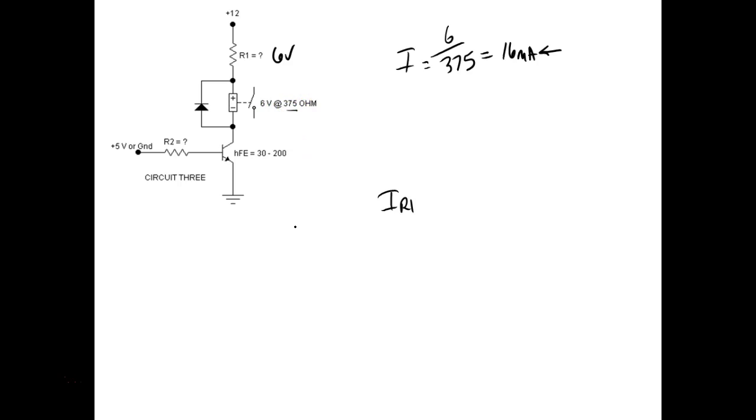We did this exact same circuit over at motor controls one time. We had a 120 volt source, and all we had was a 12 volt relay. Could we do it? Sure. All we had to do is see the resistance of the thing and do what? Calculate a resistor, put it in series that dropped all the rest of the voltage.